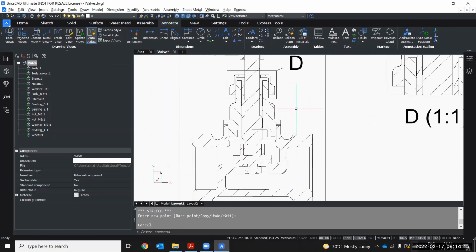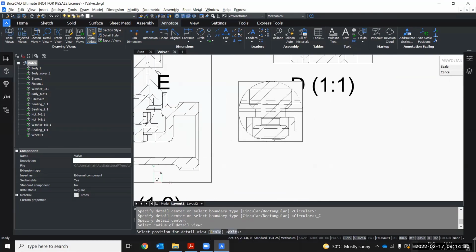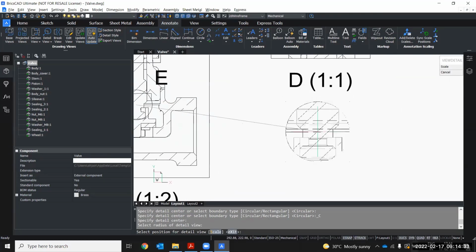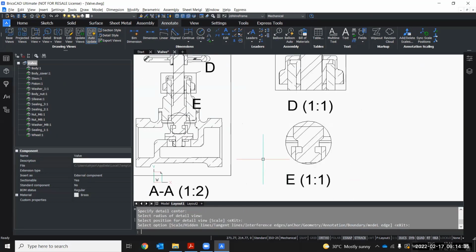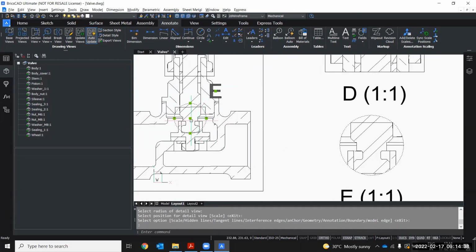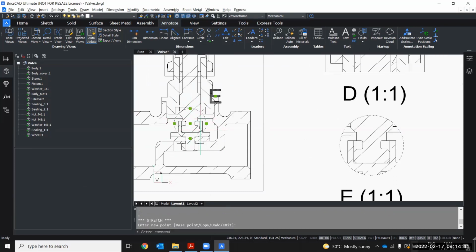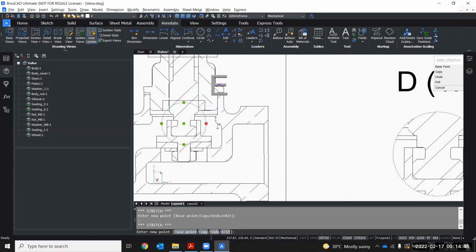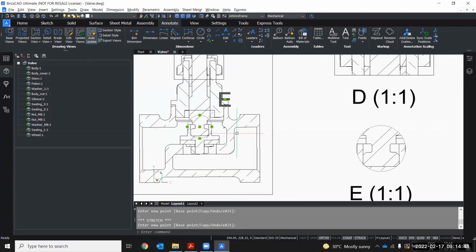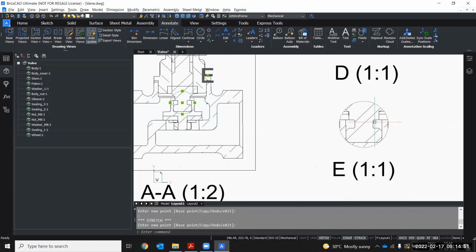Okay. The same thing you can create with a circular section wherein you can select the view, place a circular round, select the center, snap at it, and let's say you want to create a circular view. So you can place it across over here, right? And once you're done, you can simply drag or reposition it for the type of detail that you would want to see. You can increase or decrease the size of the view, the circle, and accordingly my detail will get updated.